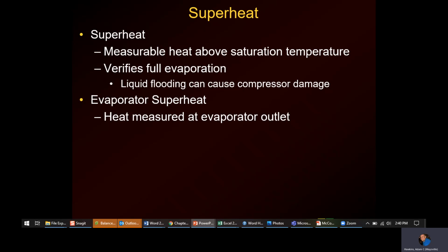And so that excess superheat gets transferred into the refrigerant, which then gets transferred to the compressor. That compressor has to be cooled by that suction gas. And you'll hear me talk about this in the compressor unit, if it gets above 65 degrees, most compressor manufacturers say that's as high as you want that gas temp to be. So if you've got 40-degree refrigerant temp and 25-degree superheat, then you're at 65. So you've got to try to keep that extra superheat down in that line set. And if that means additional insulation or whatever, then that may be what you've got to do.